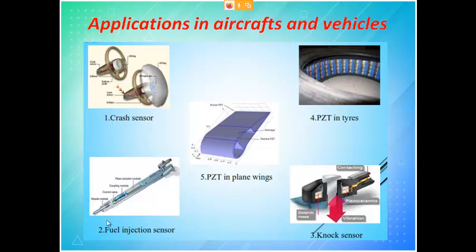At this very high compression, I will try to ignite the petrol with the help of a spark plug, and it will spark there. Your petrol will burst, and the power is more than sufficient to make the piston move down, and you get a rotational motion, okay. But nowadays I don't have inlet valve, outlet valve and all. Instead I use a piezoelectric material to measure the pressure, and if the required pressure is reached, then I will ignite with the help of a spark plug, okay. This is in case of a petrol engine.